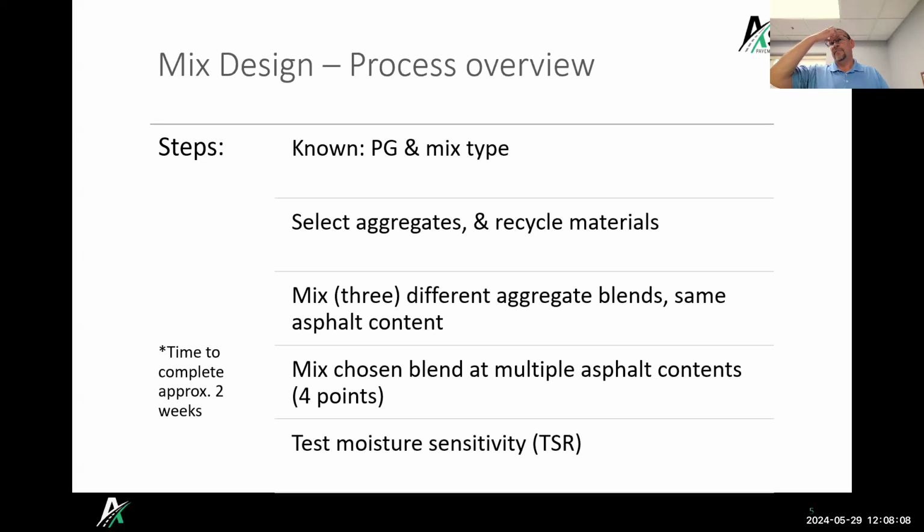So yeah, if you're doing a local agency project and you specified the same 5 EL mixture that was used on an MDOT job last year, in the same plant and everything, that mix design should be fine. And you should be able to look at it and see that it was approved by MDOT. So then you have that assurance that they've tested the material and made sure that it's going to meet specifications.